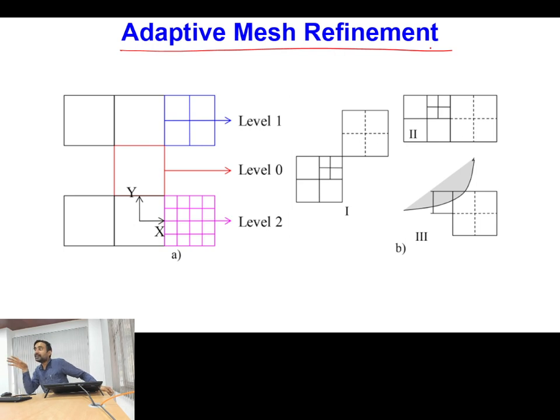The gradient of the volume fraction gives me the indication that near these cells the interface is present. On the contrary, it may happen many times that along with the interface you have some rotating or fluctuating components of velocity. So in a generic solver, the gradient of volume fraction alone is not responsible for mesh refinement. You can use the gradient of any other field parameter, say gradient of velocity or gradient of pressure or another field variable, to go for your adaptive mesh refinement.